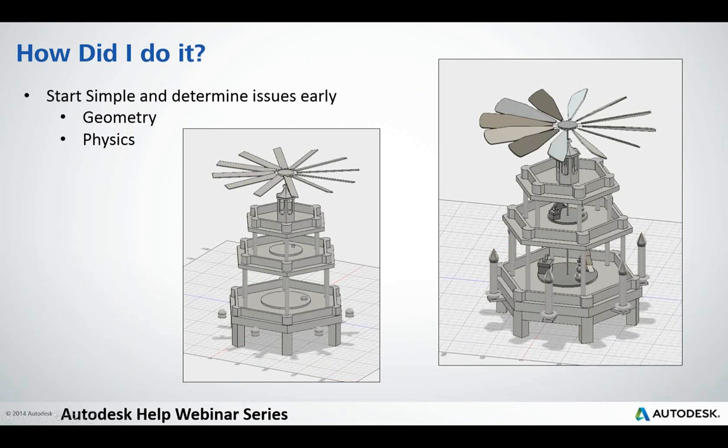So quick rundown of how I did it is very similar to the way that you should approach every engineering problem. I took the minimal that I needed for the geometry and brought that in to do my tests for the physics and figure out where I'm going to have some problems. If I'm going to have meshing issues because of the way that I had created some of the geometry, at least I don't have very detailed geometry that I have to troubleshoot while I'm figuring it out, and I can get some of the mesh settings and anything that I need to do with the physics, because this is actually a fairly complex problem. I'm running a heat source causing buoyant flow, and then running with flow-driven motion. So by all means, not the simplest of analyses to set up, and the more troubleshooting I can do on something that runs faster, the more likelihood I'm going to have success in the end.